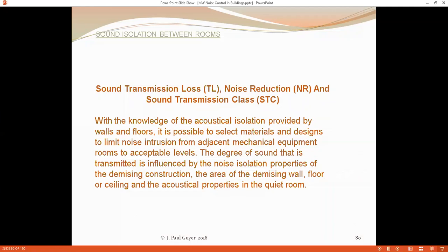And so what you have done there is you have broken the solid material path of the sound, the acoustic energy, going from the source room to the receiving room. I said at the start that sound is primarily a through-the-air phenomenon, but sound also does get transmitted through solid elements in a building system. So, staggered studs.